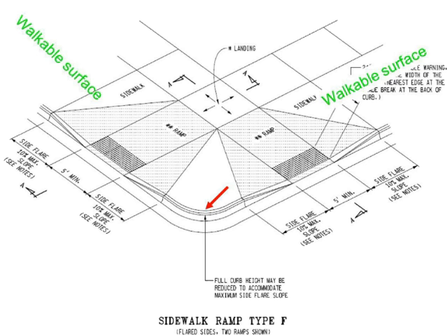Talk a little bit about side flares. When you've got some of these wider sidewalks, downtown areas, that come to the back of curb, if you've got a walkable surface that's going to cross the ramp, you don't want anybody tripping over. Again, it's not necessarily for persons with disabilities. It's for you and me, people who walk around not paying attention, or you're texting and walking at the same time. You don't want to be falling over.